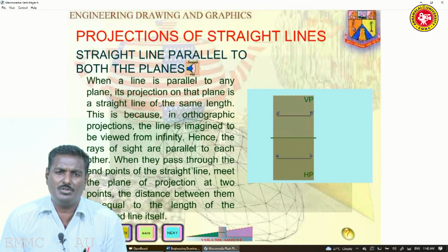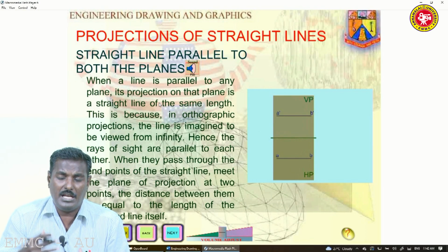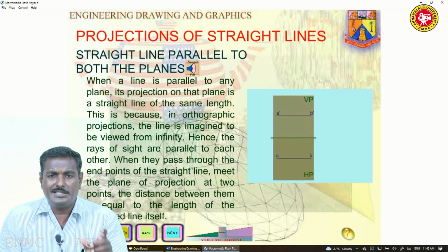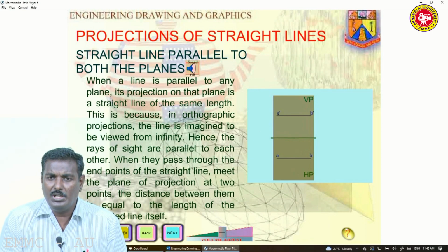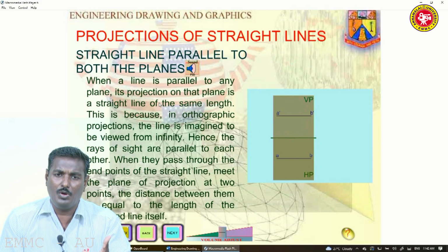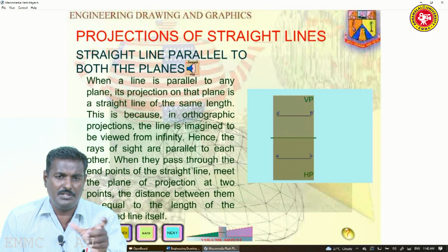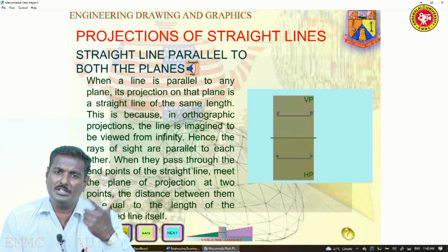The remaining two are not helpful because of overlapping, as I already stated in the theory of projection. Due to overlapping, second angle projection and fourth angle projection are avoided, so we use only first angle and third angle projections. Some countries follow third angle projection; even in India, manufacturing uses first angle, but civil and other types of construction work follow third angle projection.